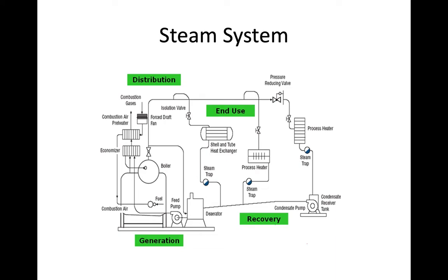So we have to prevent minerals from entering the boiler system, so we need a water treatment plant to treat the boiler feed water.